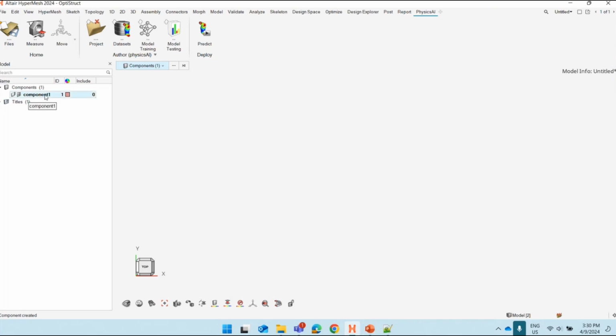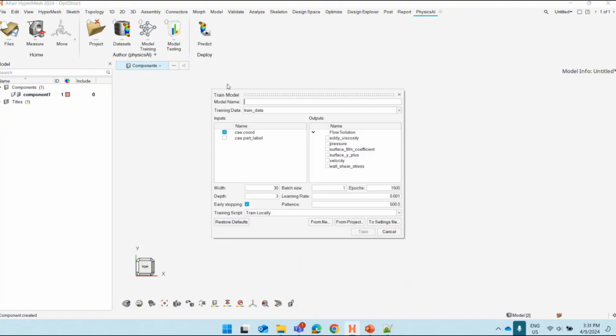What's the purpose of this? If you observe, we are actually using nodes as shape variables, right? If the nodes are variables, and let's say all my models are just skin elements, just 2D shell elements, how does it detect thickness? Because you can see here, I don't have property thickness. So that means I cannot take the property thickness as a variable.